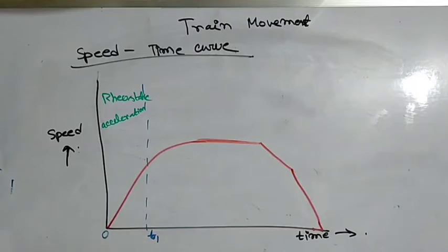Now tractive effort is defined as the force in newtons exerted by driving wheel on the rail to produce the movement, and sum of tractive efforts exerted by all the driving wheels of a locomotive is called gross tractive effort, which is proportional to the combined torque exerted by the motor. Now motor current during the notching up period fluctuates between certain maximum and minimum limits, and therefore torque developed by the motor and the tractive effort also fluctuate.